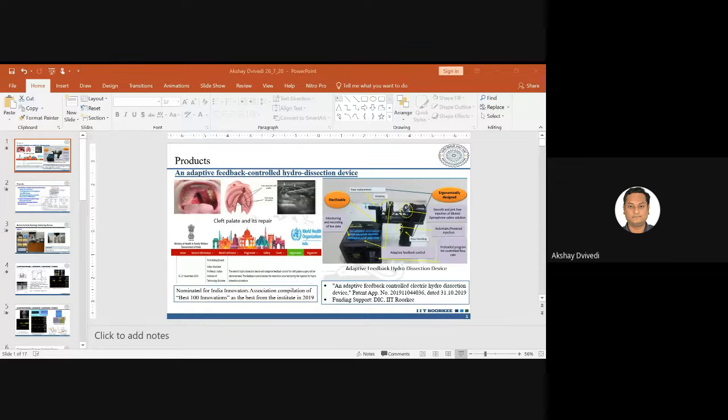The idea came up into development of something which is named as tool roughening system for electrochemical discharge machining process. Now, how did we actually start with this particular thing? For that, we had a simple electric discharge machining process. In this process, you have a tool and you have a work. The tool is usually given negative polarity, and the work is given a positive polarity.